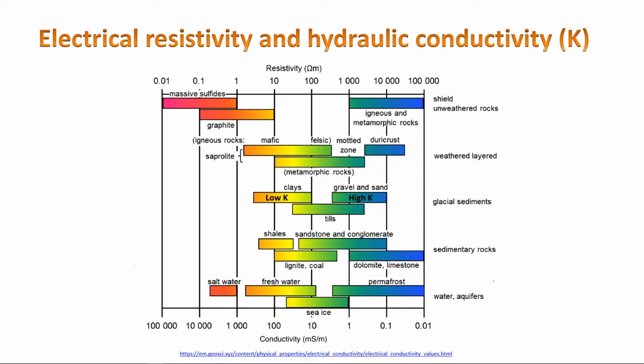So water and gas pipelines, electrical conduits, sewer pipelines. To prevent accidental damage during excavation, you can conduct this electrical resistivity method to identify these features, because they will have an anomaly compared with the surrounding material. Yeah, so that would be environmental engineering. In structural and geotechnical engineering, there are a lot of applications.